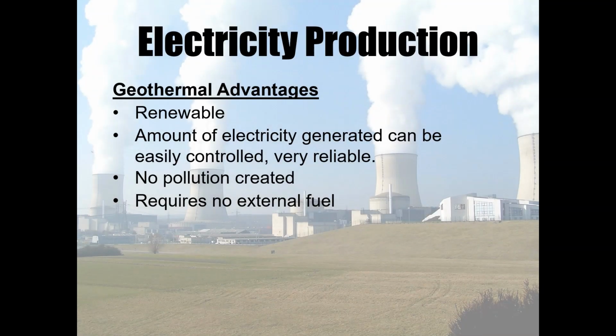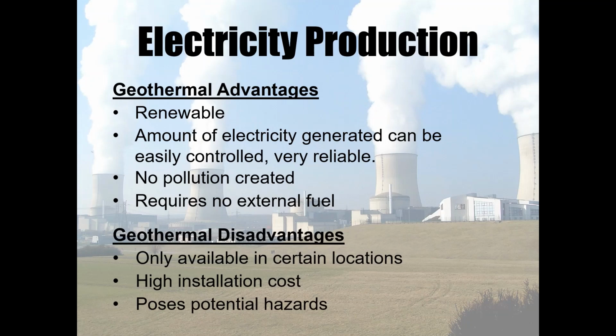Okay, geothermal, obviously again it's renewable. The amount of electricity being generated can be easily controlled, and again no pollution created, no external fuel sources, all really good advantages. Disadvantages: also can only be used in certain locations. We need somewhere where the Earth's crust is thin enough for us to be able to actually get down, but it also depends what the Earth's crust is made of. If you're in a region like Jersey where it's granite, it's going to be very difficult to drill through it in order to get down deep enough to be able to make anything useful. So effectively it rules out using geothermal in Jersey.